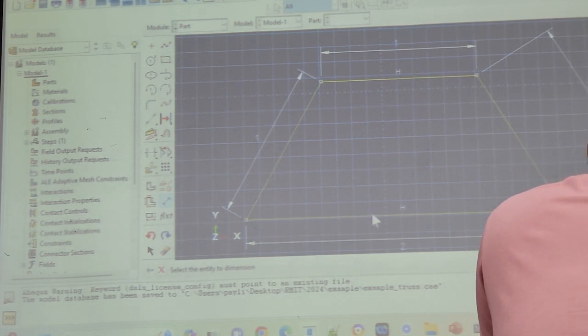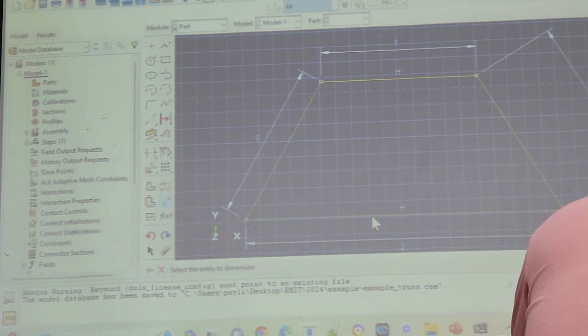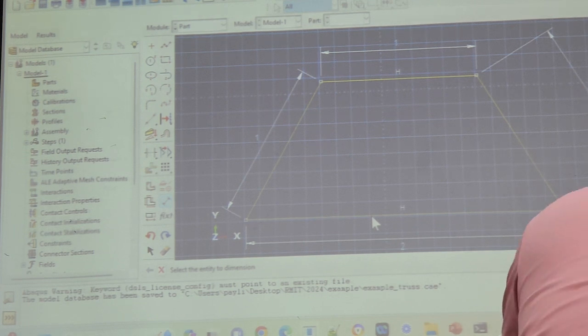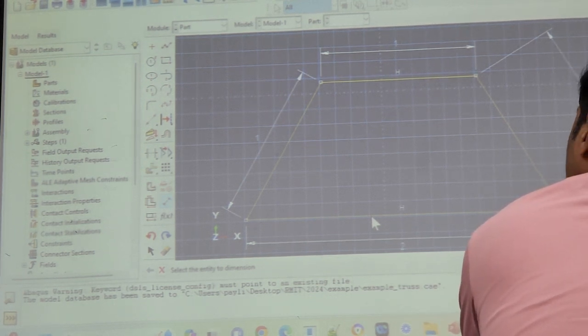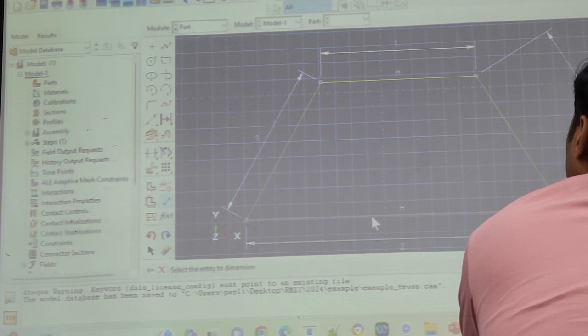Then just now we said, can't you see this is one member on this one? Does it work? Why? Because we have to look at the figure to see how it elongates. If it's one member, then the triangular diagonal braces will not restrict anything. So that's why we need to break this. Hey, you all seem very interested in trying on your own.